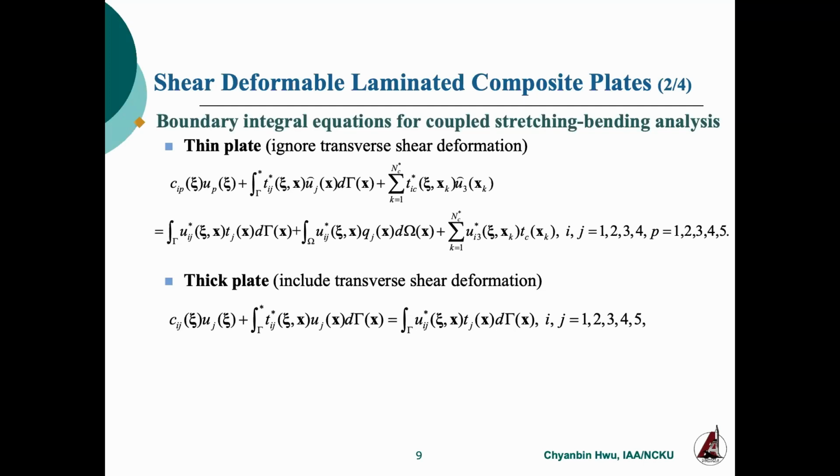For the thick plate, the boundary integral equation has exactly the same mathematical form as a two-dimensional analysis or three-dimensional analysis. So if we can develop the boundary element based upon the thick plate, it will be simpler than the thin plate. Even though the degrees of freedom are higher than the thin plate, it will be simple.